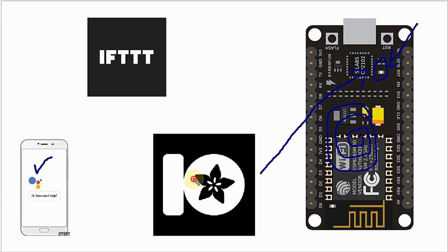We just created a toggle button in the Adafruit IoT platform, and using that toggle button we are providing the MQTT request to turn on the LED connected to GPIO16 of the ESP8266 board. This program is already running in ESP8266. We will not touch anything over here. This will be stable, and the dashboard in the Adafruit platform will also be stable. We will not touch this part in this video.